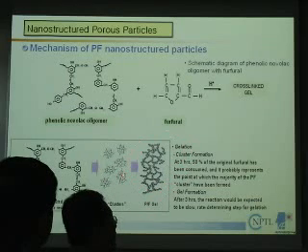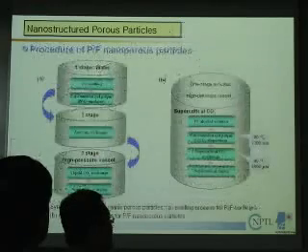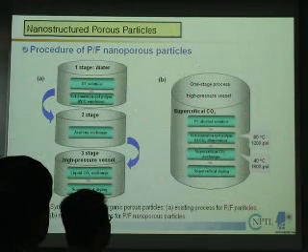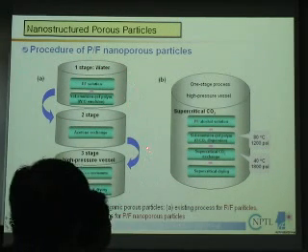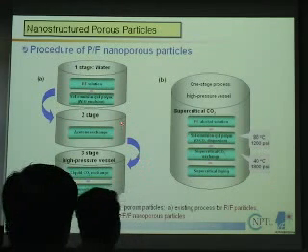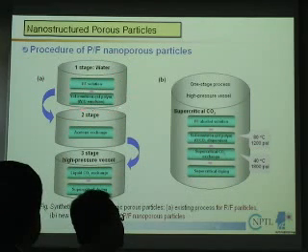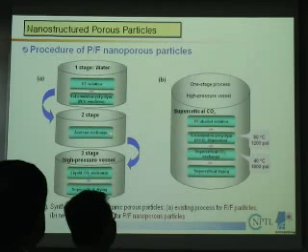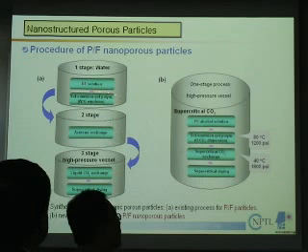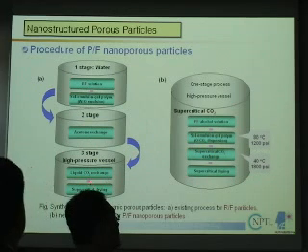So you may be familiar with how to make the aerogel. This one is our approach, and this is the conventional way of making aerogel particles. Normally it takes about 3 to 4 days, and it's very tedious because in the first stage you have to make the gel by doing this reaction. In the second stage, because of the density difference, you have to exchange the water in the gel with acetone, and then extract that acetone using supercritical fluid to make the porous particles or porous materials.